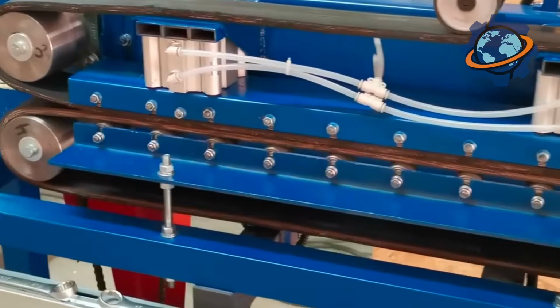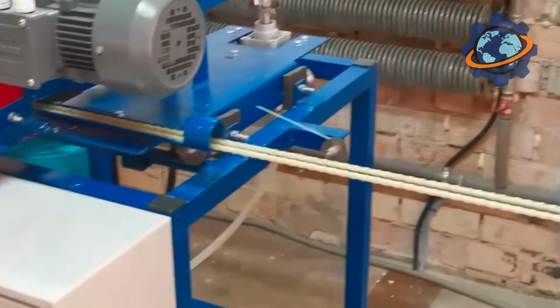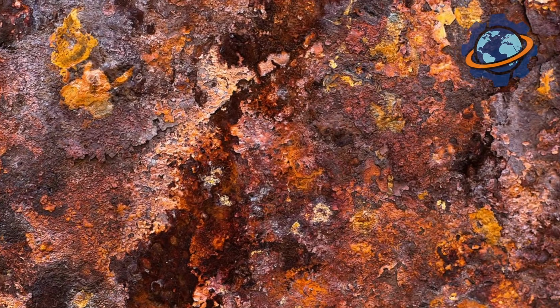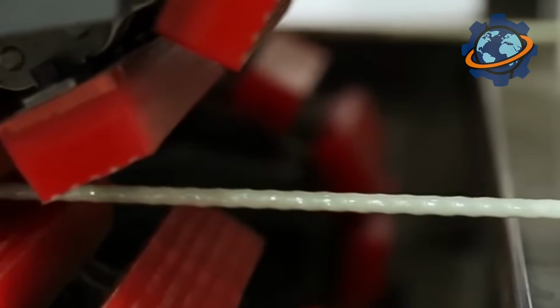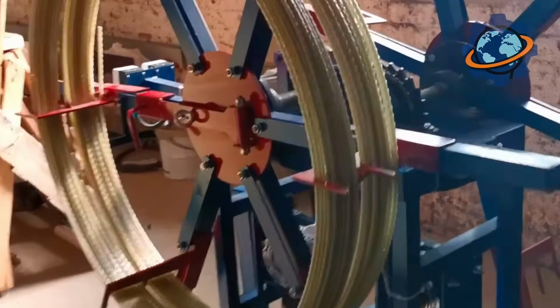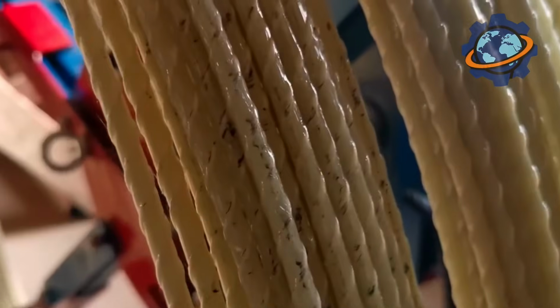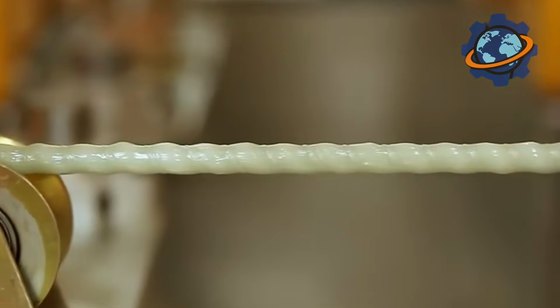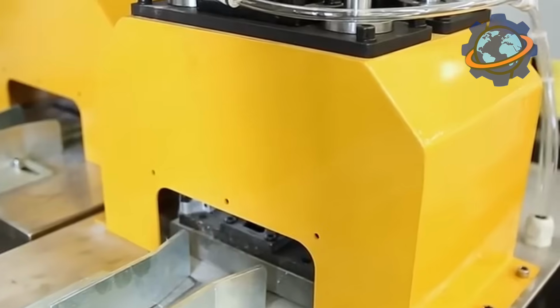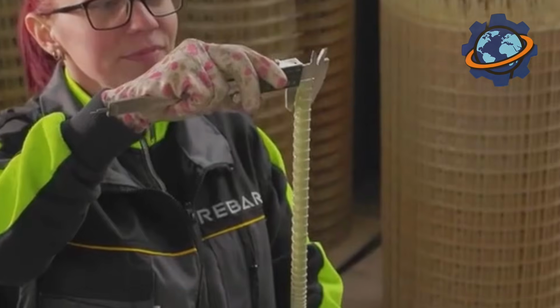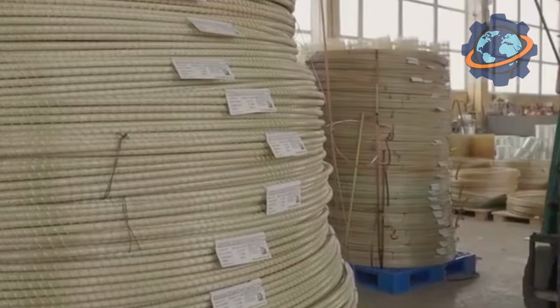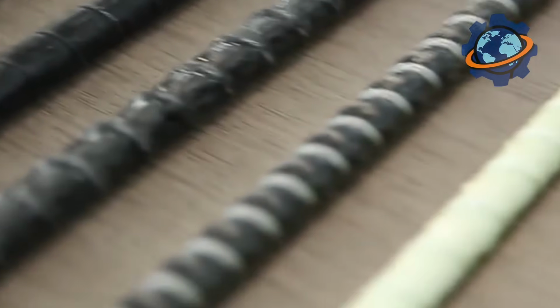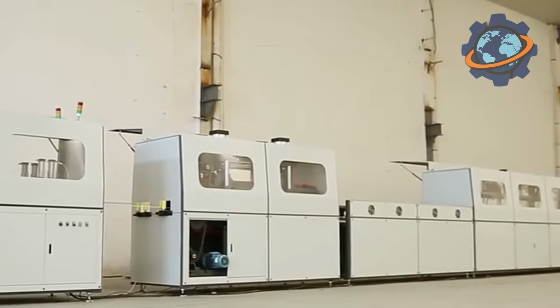But the main trump card, the real superpower of fiberglass, is its war against rust. The main enemy of any reinforced concrete structure, from bridges to parking garages, is not the load. It's rust. Water and salts penetrate through micro cracks in the concrete, reach the steel rebar, and it begins to rust. The rust expands in volume and literally tears the concrete apart from the inside. Annually, the US spends billions of dollars on repairing bridges, parking garages, embankments, and tunnels destroyed by rebar corrosion.